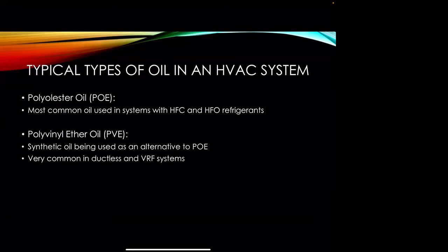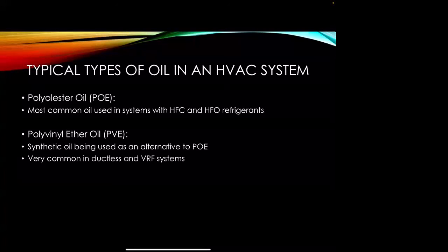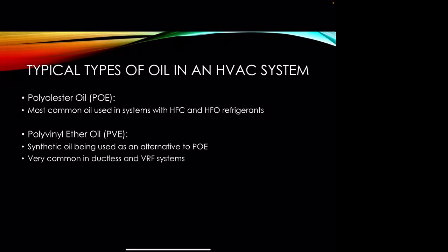In 2023, we're going to have a change. In Kentucky, the minimum SEER rating on air conditioners to be installed is going to be 15. In Indiana, Ohio, Illinois, some of the northern states here, the code is going to change from our 13 SEER to 14 SEER. There's also Puron Advanced, which is what it's being labeled as right now, and that is R454B.